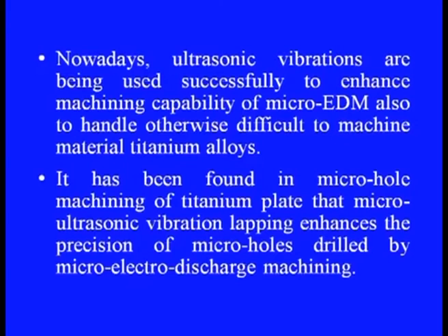It has been found in micro hole machining of titanium plate that micro ultrasonic vibration lapping enhances the precision of micro holes drilled by micro electro discharge machining. Further, USM assisted turning is also claimed to reduce machining time, workpiece residual stresses and strain hardening, and improve workpiece surface quality and tool life compared to conventional turning.